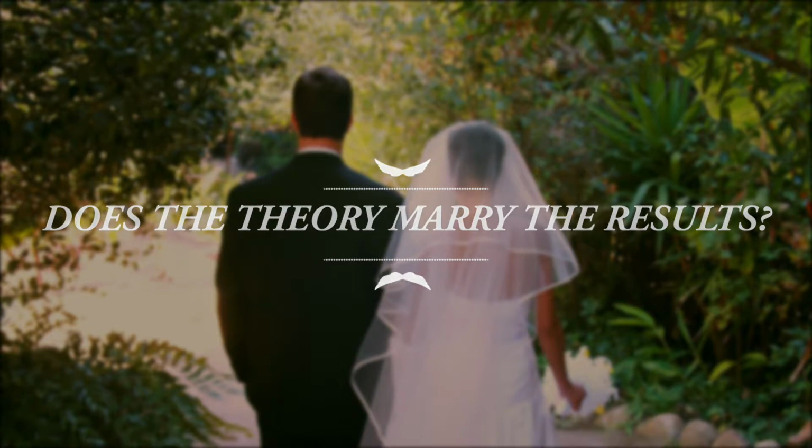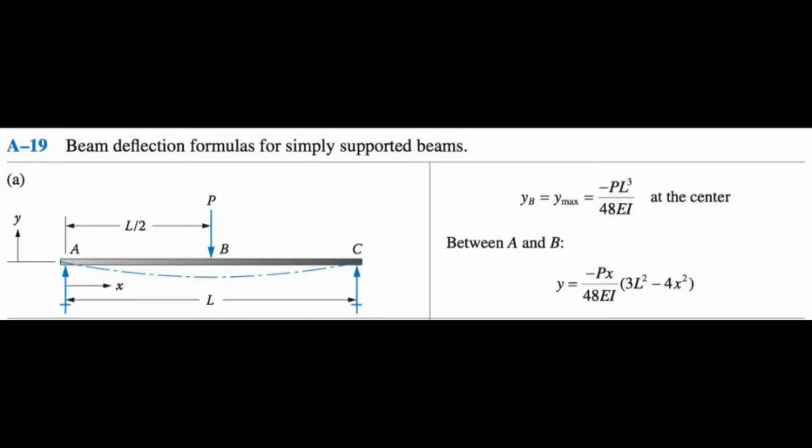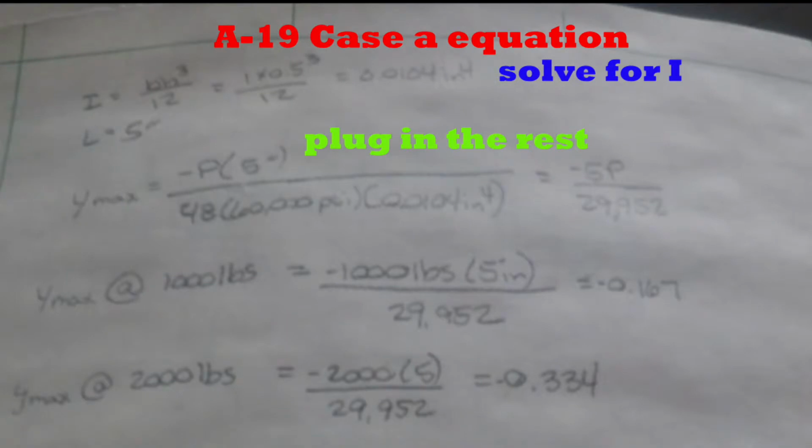Now, let's see if the theory marries up to the experimental results. By using the formula in Appendix A19, Case A, we can derive our expected results. By solving for I, all we needed to do then was fill out the rest of the formula using length equals 5 inches, I equals 0.0104 inches to the fourth, and for P, the incremental load.